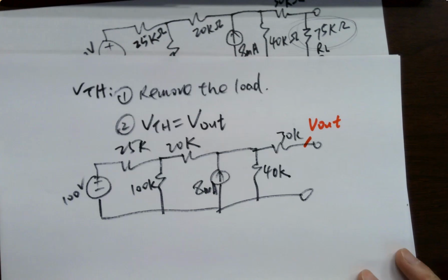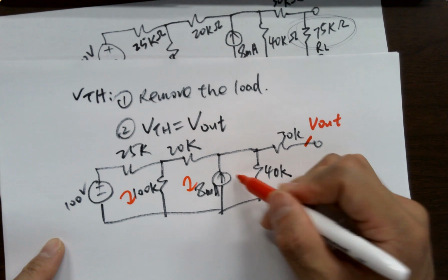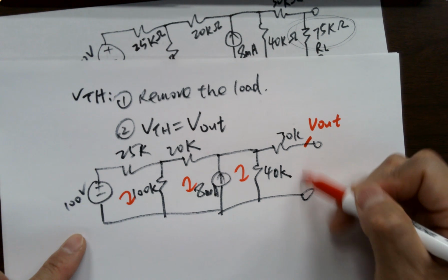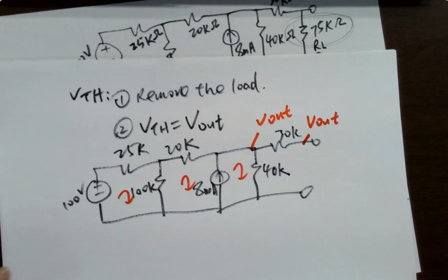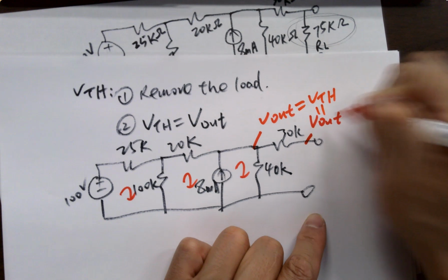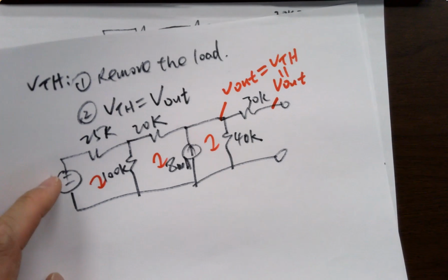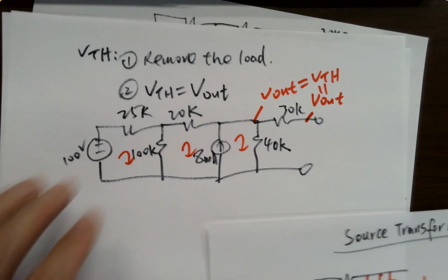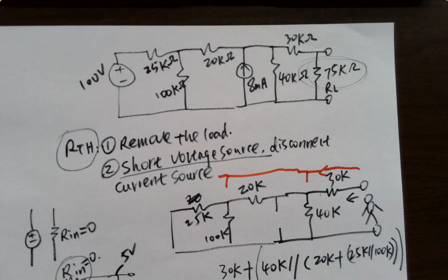Have you learned how to find it? Yes, we can use many different methods to do it. Node voltage methods, mesh. Okay? Is there any current flowing through it? No. The load is removed. So V out is the same voltage here in this case. Okay? So this is VTH. VTH is found. RTH is found. Just build a circuit like this. That's the equivalent circuit. You can replace the whole thing with this equivalent circuit. All right? Okay, we'll see you on Wednesday.